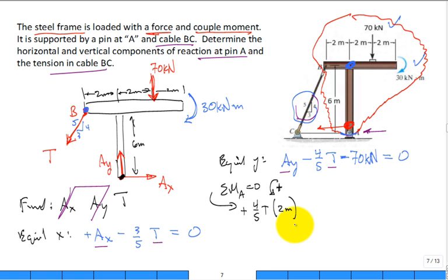All right, now let's pick off the 3/5 T, right? So it's like we separated this into the 4/5 and 3/5 T, applied at point B. And what is the moment arm distance for that 3/5 T? 6 meters. Excellent. And will that give it a positive sense of rotation around point A or a negative sense of rotation? Positive. That's right.